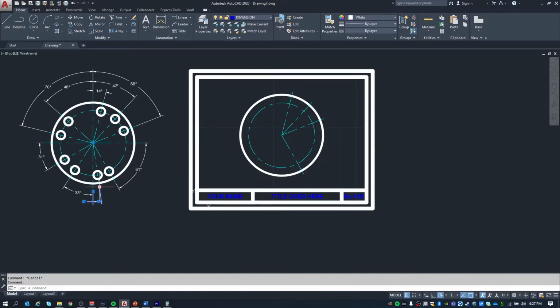Okay, this next one shows it being 8 degrees from the minus 90. So if we go minus 90 and add 8, we're going to get minus 82 degrees. So again, line less than minus 82 at 2.75 long. Oop, I made a mistake. Try that again. So we're going to do line less than minus 82. There we go, at 2.75 long.